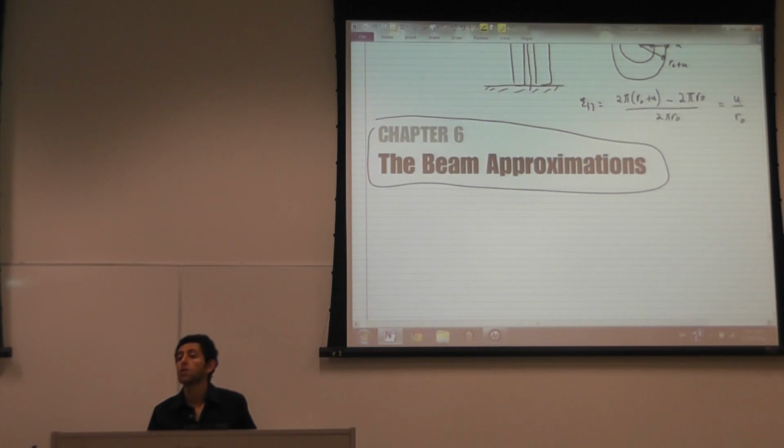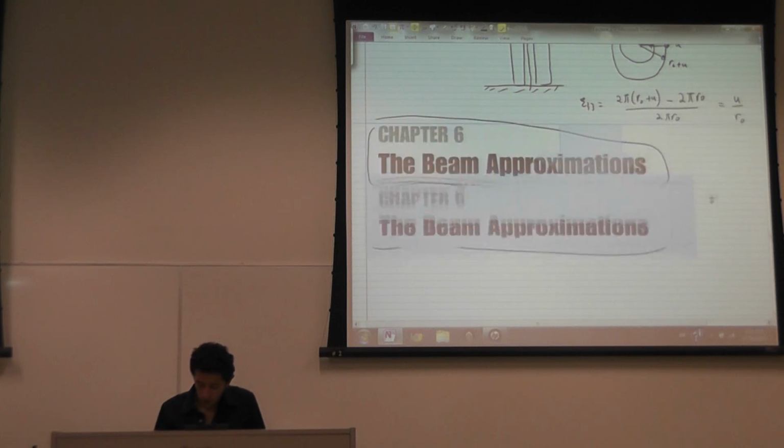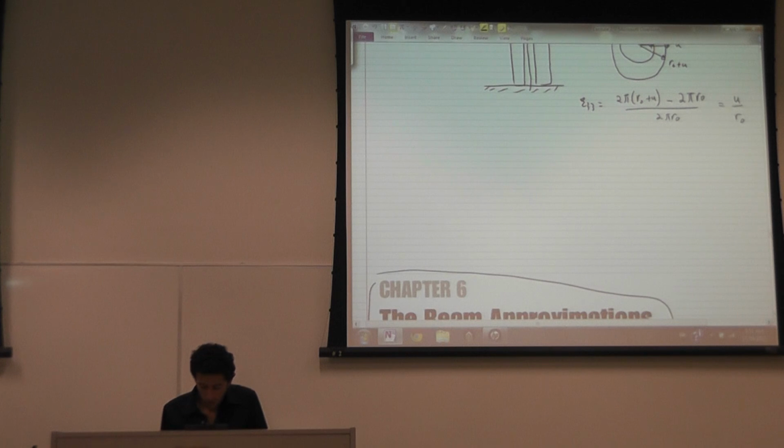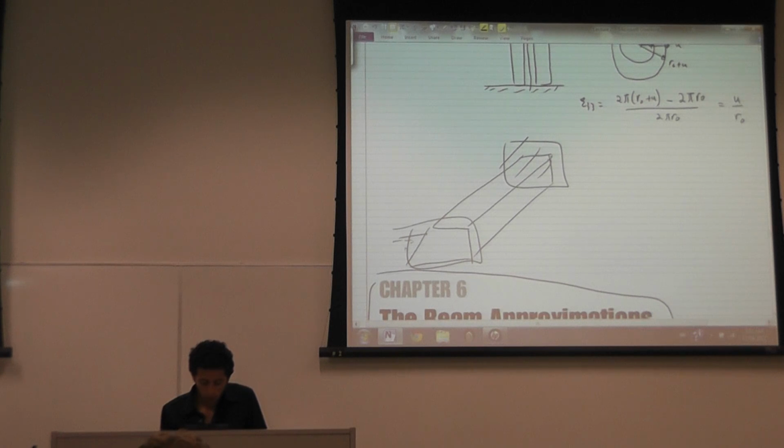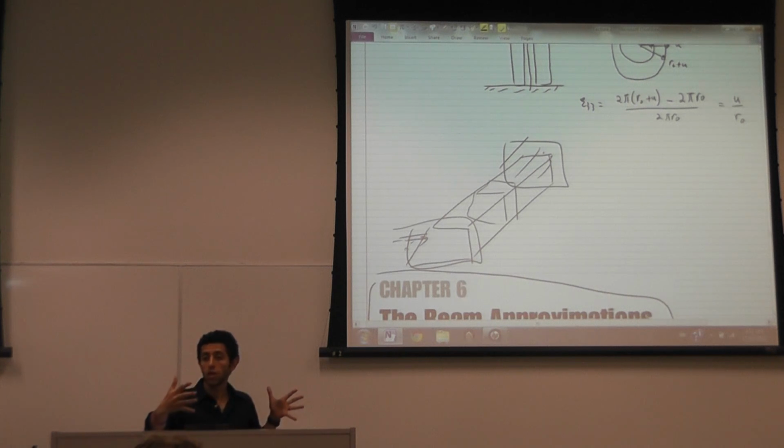Plane strain condition, consider dams, for example. If you have a really long dam, with load fluid acting on it in this direction, away from the support, I consider it a plane strain condition because I'm preventing the dam from expanding or contracting in the third direction. So any really long object that's constrained in the third direction is in a plane strain condition.